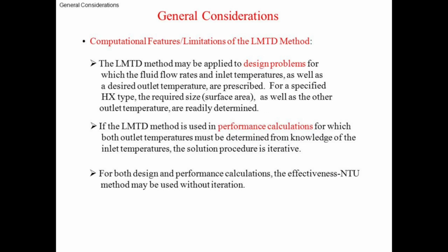Thus, the heat exchanger can be designed by the LMTD method when inlet and outlet temperatures are known, but when it is required to determine the inlet or exit temperature for a particular heat exchanger, the analysis is more easily performed by using a method based on the NTU method, the number of transfer units method.